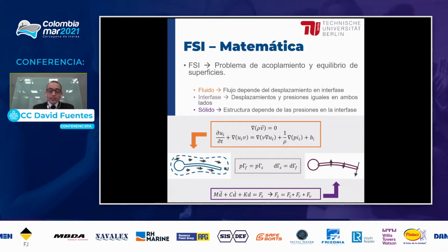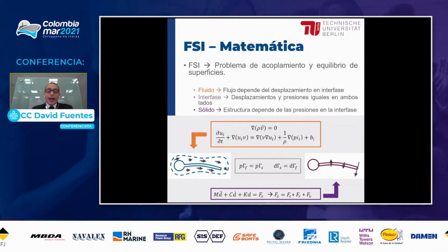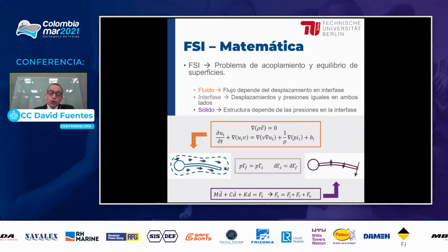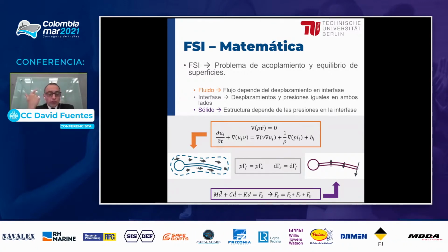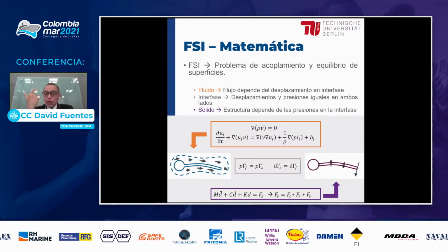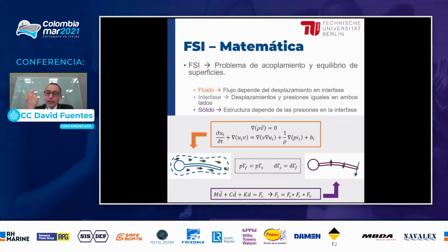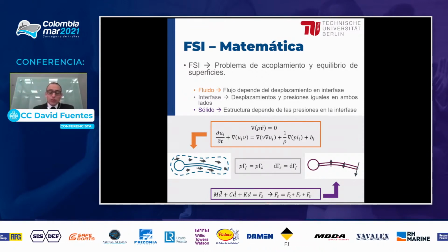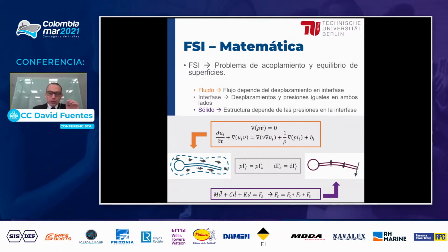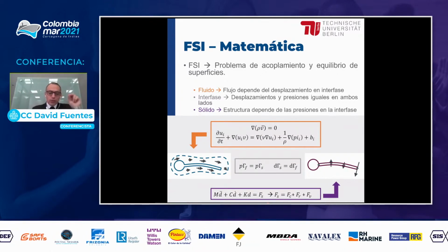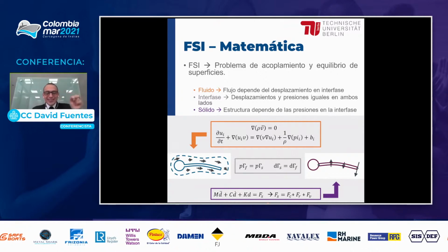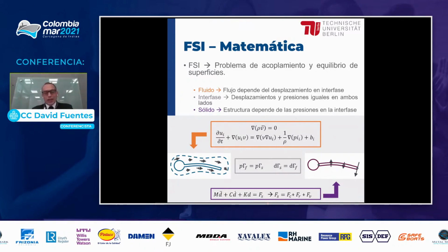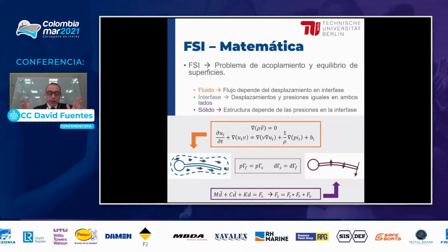Regarding the fluid dynamic code, this code solves the equations that resolve the flow very accurately and considers the flow as incompressible, with pressure of the mass and the force, calculating pressure and hydrodynamic loads from the point of view of the structure. The displacement equations are solved in the nodes, and the size of the matrix will depend on the amount of nodes and elements that are obtained.